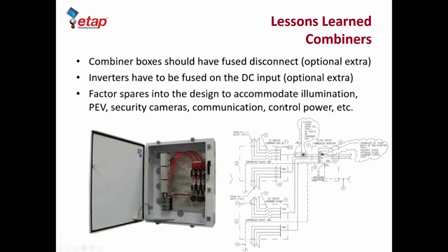It's good practice to always make sure that there are sufficient spares or conduits provided to accommodate illumination, any plug-in electric vehicles, security cameras, plus the communication and control power, because the combiners themselves may not be self-powered. They will require control power, 12 volt or 24 volt DC input, and that has to be provided from the facility to the combiner box itself.